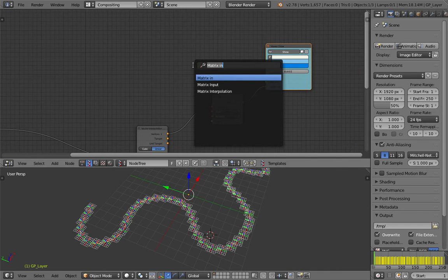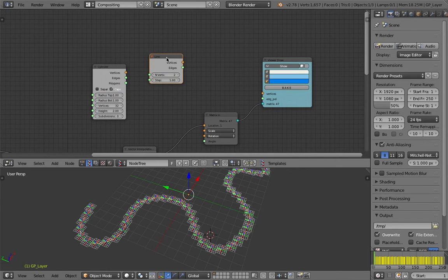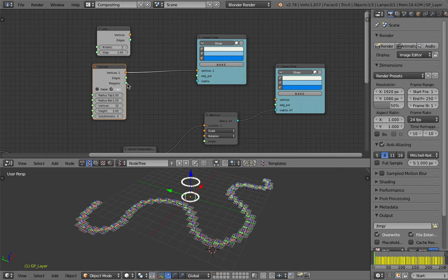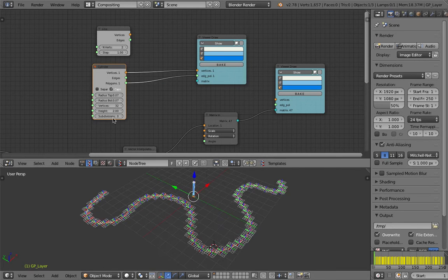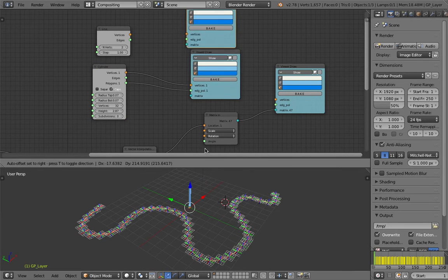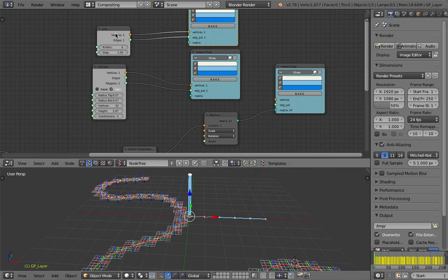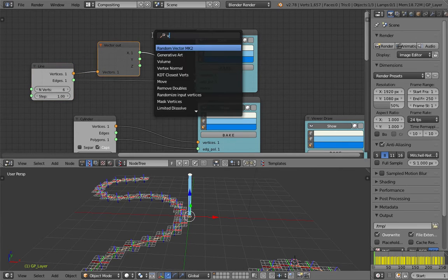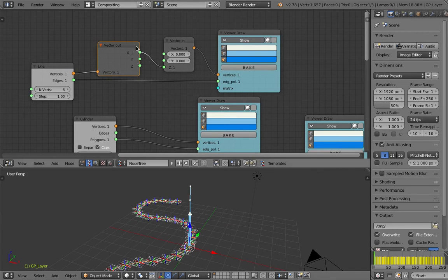For simplicity, you can use cylinder or you can use line. Cylinder, by default, actually grows upwards. If you see here, okay, that's a cylinder. We want it definitely a lot smaller like that, and we want to control the height. So cylinder grows in the z direction, which is good, while the line, if we use line, grows in the x-axis. And since we don't have control over the axis here, you can use vector out, vector in, and pipe the x into the z, so that now it's going up.